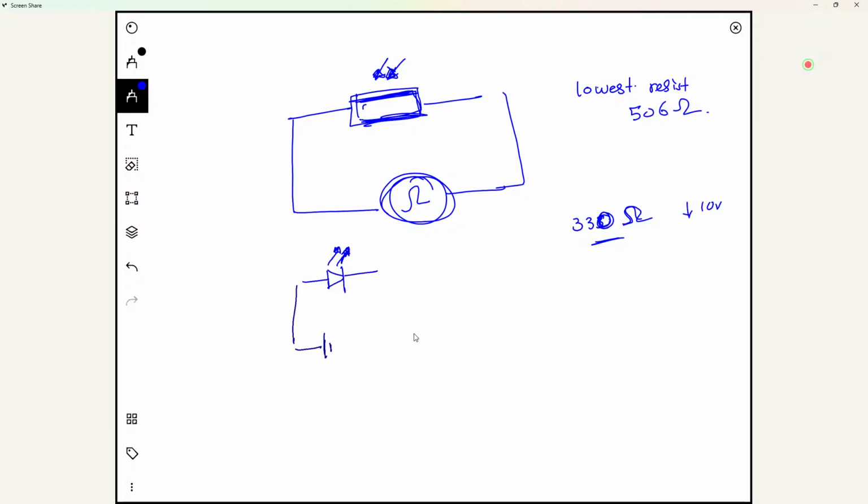You cannot do this. Why? Because the working voltage of the LED might be around 1.8 to, let's say, 3 volts, but usually your power supply will be 5, 6 or 12 volts, I don't know, but usually it will be higher than this. So in that situation, to make sure that we operate the LED safely, we always need to add a resistor in series with the LED.